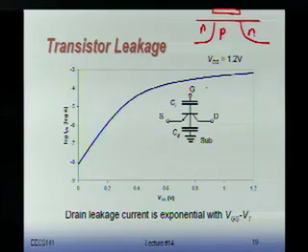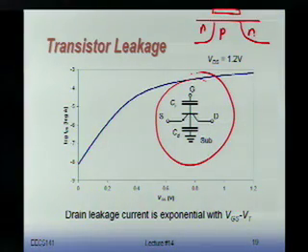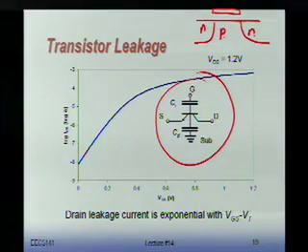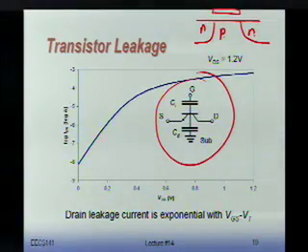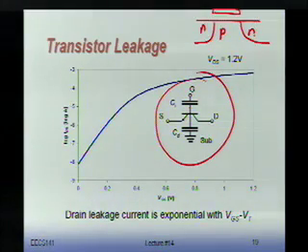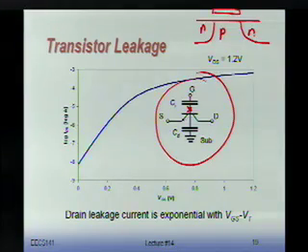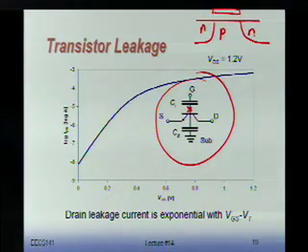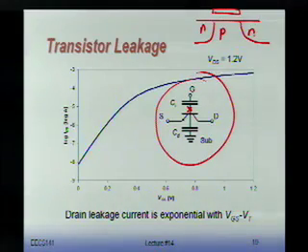But as I've shown in this picture here, this NPN forms a bipolar transistor. The bipolar transistor is kind of weird because the base of the bipolar transistor is not directly connected to the gate, but to a capacitor. So the voltage that I'm going to apply right here is going to be kind of a capacitive divider between the gate and the substrate. Okay? And that's going to determine how this current basically flows.